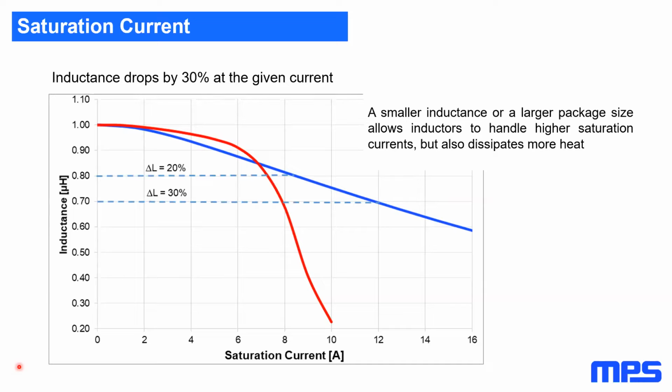And then we have the magnetic losses regarding the core material, and they are also dominating. The hysteresis loss is also a big part of the losses. This is something you don't see when you buy an inductor; you don't see the hysteresis loss in the datasheet. That's why it's always important to have this kind of measurement comparison, and there you see how the real efficiency of the inductor is.